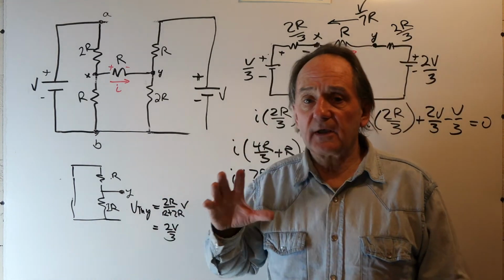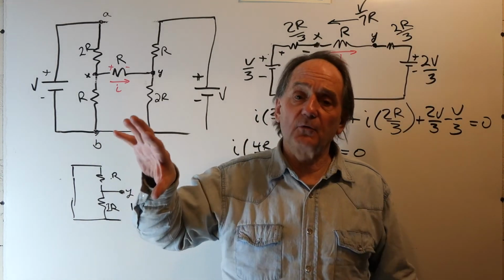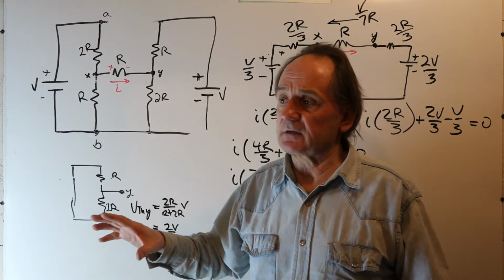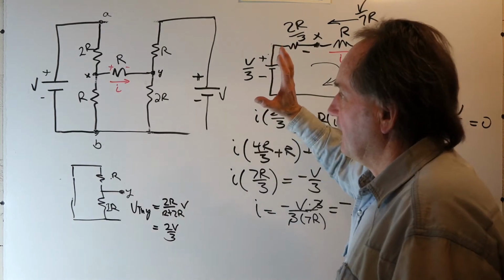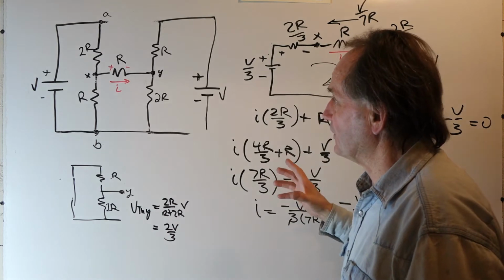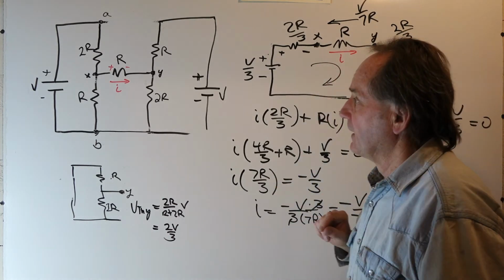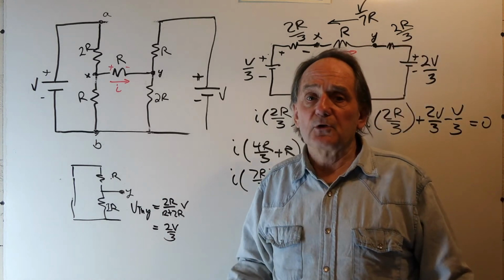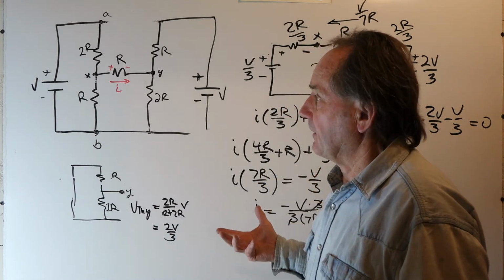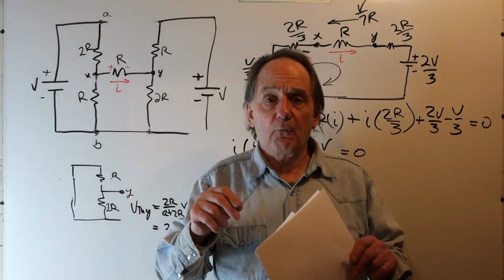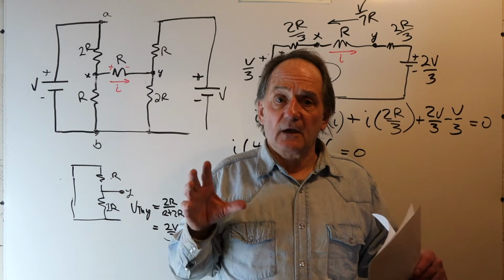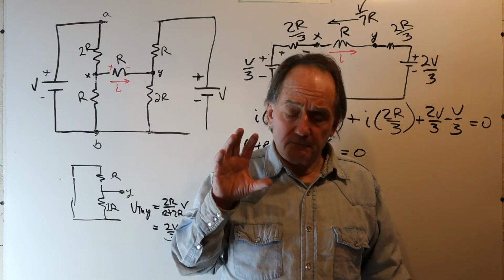You can always break a circuit someplace and look back into a circuit and find its Thevenin equivalent and simplify the analysis, if all you're focused on is a particular voltage or current like we were here. We can greatly reduce the analysis complication by breaking a network, getting the open circuit voltage, then killing all the sources and getting the Thevenin impedance.